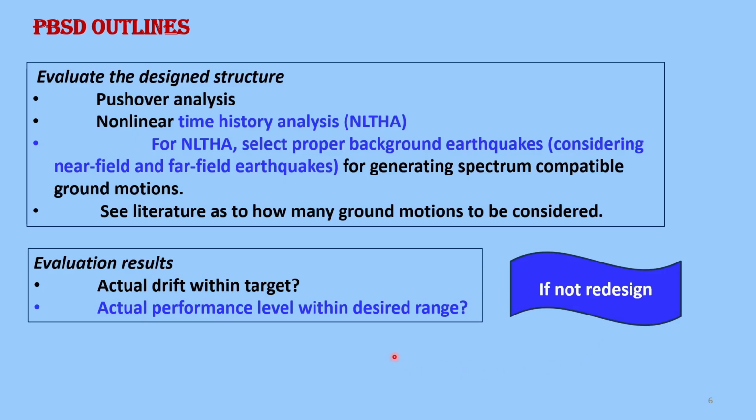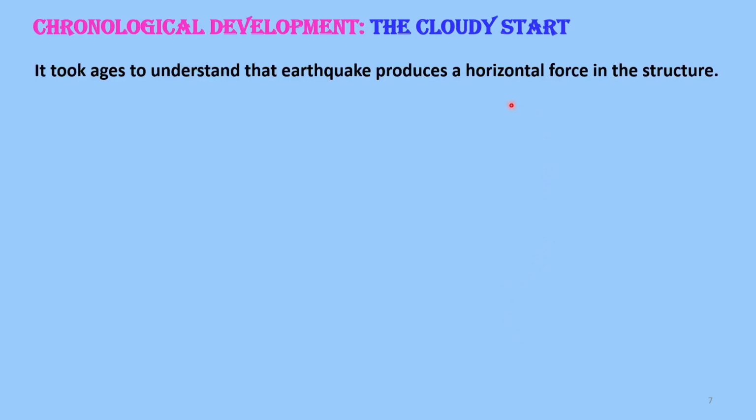Generally, in certain types of designs like direct displacement based design, you may require this iteration for design. In the unified performance based design, the member sizes are already known and it does not require iteration generally. So these are the basic two types of design we shall be seeing slightly in this video and in detail in coming videos.